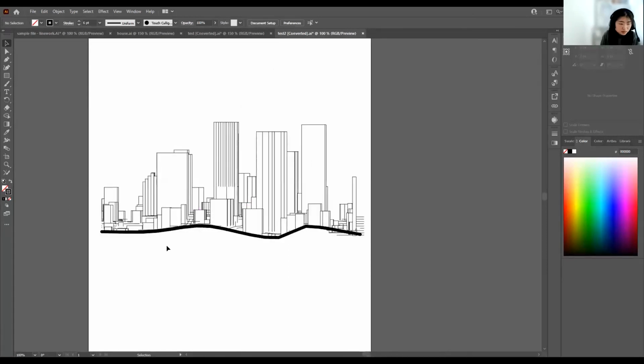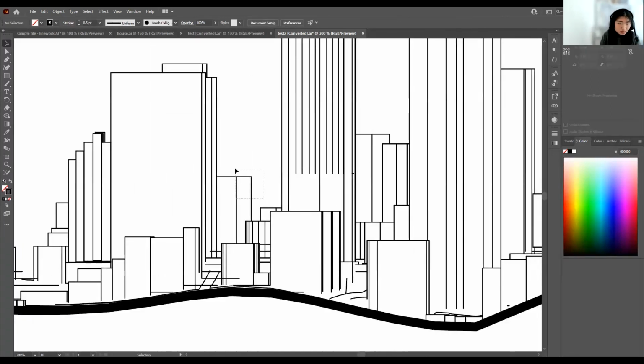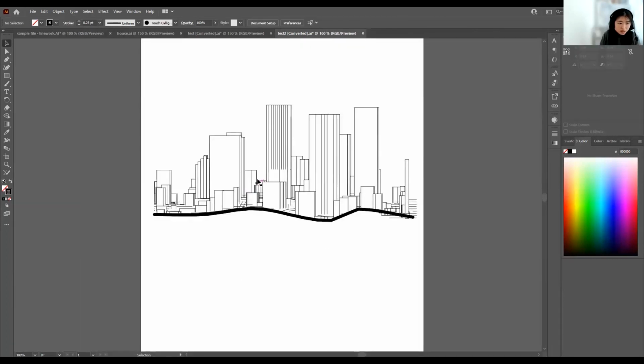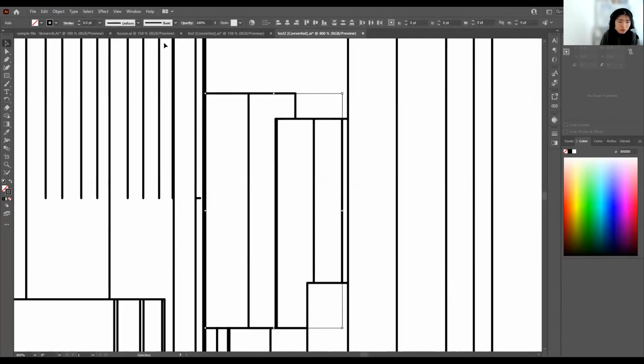And a really important thing to remember about a section, I should have done this for you beforehand, is whatever that section line cuts, that should also be in a thicker line. And then everything behind it, if you know that these buildings are behind and the furthest away, that should probably be the thinnest. And so just to give that sense of perspective, that's what I would recommend.